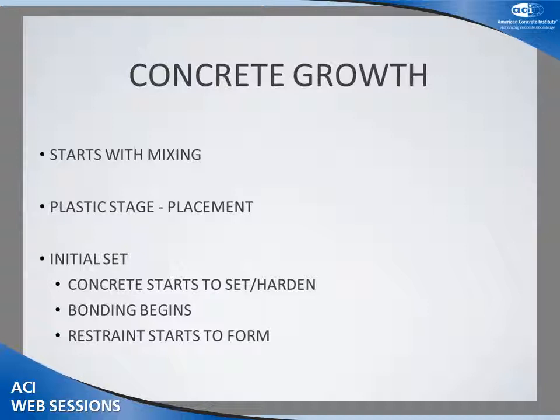The best and the most complete restraint is probably steel reinforcing, most commonly reinforcing bars, but other means of restraint are available. Restraint is the secret that makes shrinkage compensating concrete work. Restraint is the secret for eliminating shrinkage cracking. Here is how the components make shrinkage compensating concrete work.